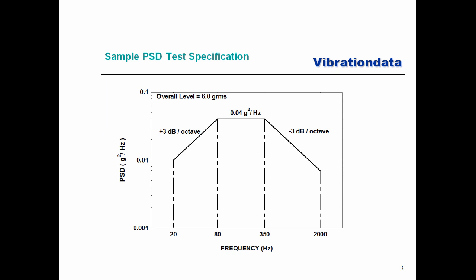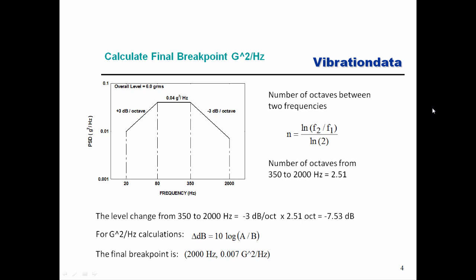And also, just as a reminder, this PSD is intended as a base acceleration or a seismic acceleration of the equipment. We can also take PSDs of force or pressure or displacement, velocity or voltage or just about anything else you can measure. But most commonly when we're dealing with PSDs, we're dealing with acceleration for design and test purposes.